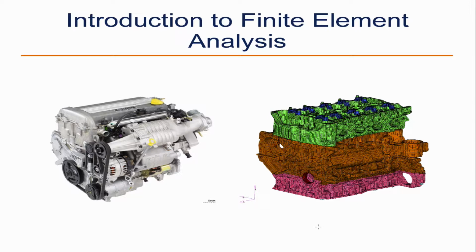And in this class, those little simple things will be triangles or quads in 2 dimensions, or tetrahedra and hexahedra in 3 dimensions. In fact, we won't ever do anything in 3 dimensions in this class because it's a straightforward extension of 2D. So the discrete things we'll break them up into will be triangles and quads. A quad is a four-sided thing, but it doesn't necessarily have to be a parallelogram or a trapezoid. It's got 4 sides, but they could be arbitrarily oriented, okay?